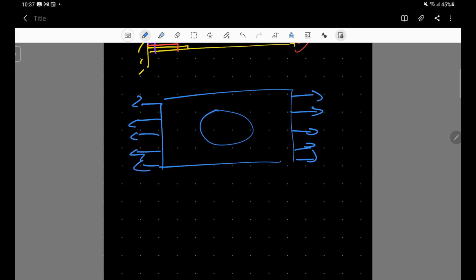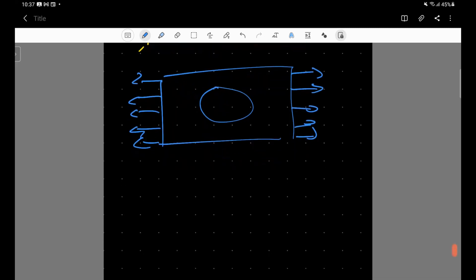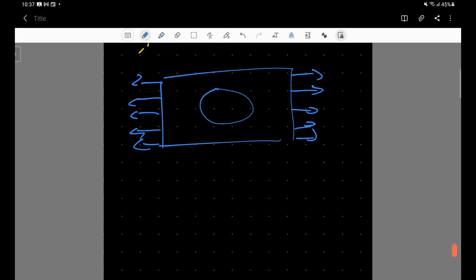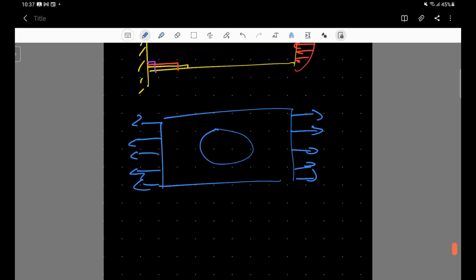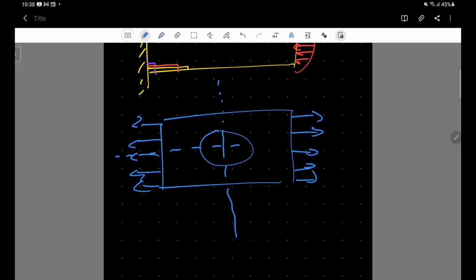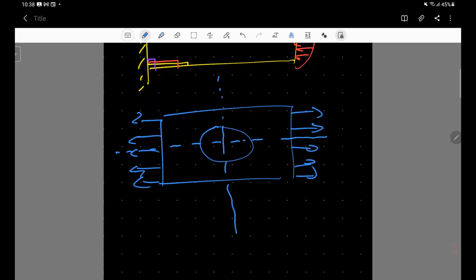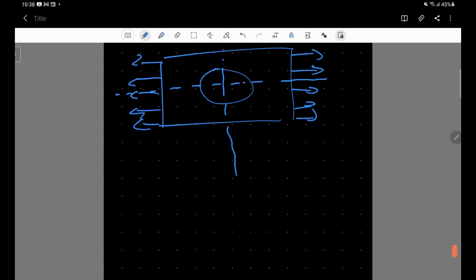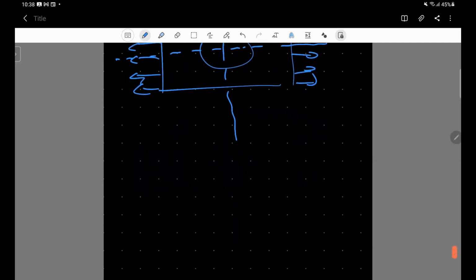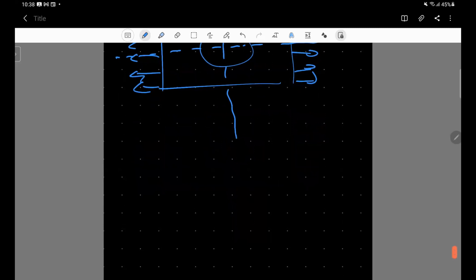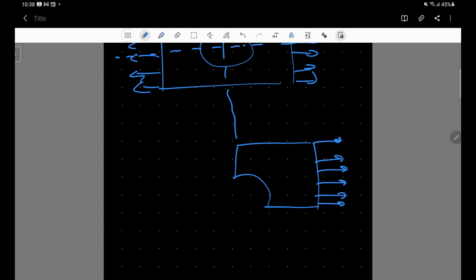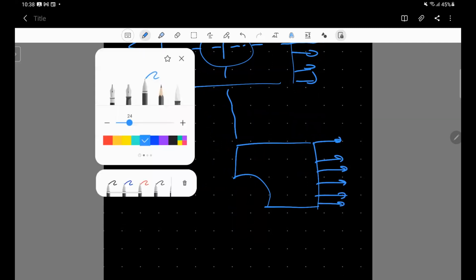I assume that you used the complete model in order to perform the simulation. If you are careful enough, you would be able to see the symmetry of this problem, in two directions, and of course, you can use this symmetry to develop a model by applying the corresponding proper boundary conditions.